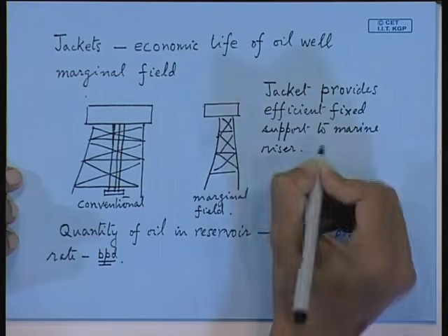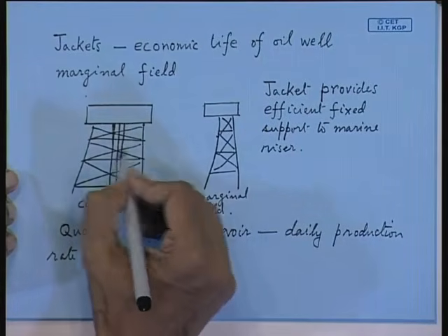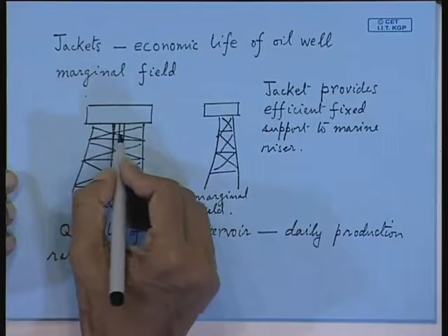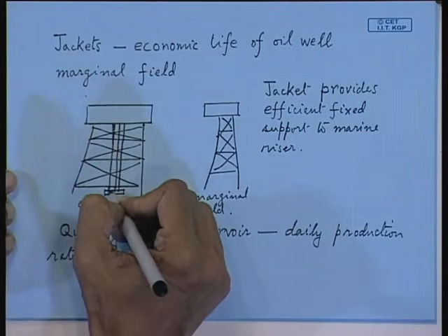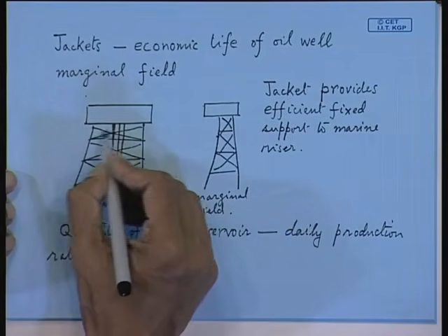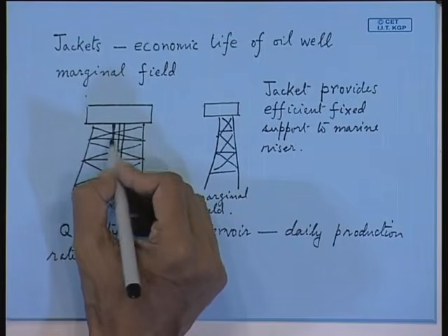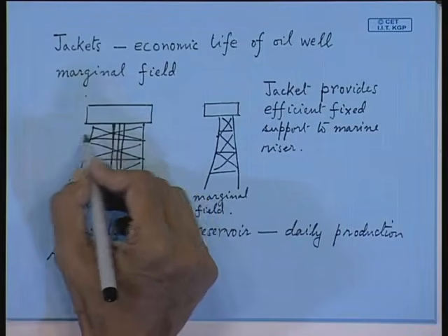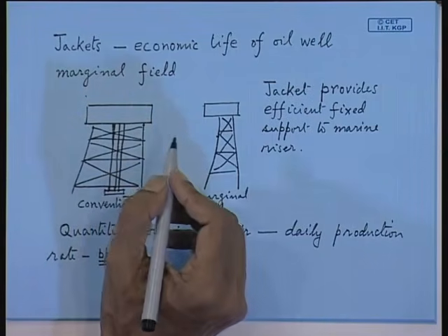Now, you can go on increasing the size of these pipes, along with the size, weight of the pipe. What else you will find is that the marine riser is also encountering larger wave loads. As soon as you increase the diameter of this pipe, the wave load is also going to increase, isn't it?